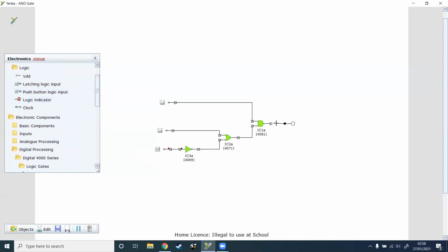If you look at page 14 of the course notes while you're doing this, you'll see this is the same circuit, and we can test out all the various scenarios. This is one of the things you do in the assessment. You'll be building a circuit, but you'll also be testing it to make sure it meets the criteria. One of the things we wanted to happen is the alarm system doesn't go on unless the master switch is on. So you can see I can toggle the light beam broken or not, I can toggle the pressure pad, I can do a combination of both, but that right-hand indicator light is not going on. So currently that seems to be working.